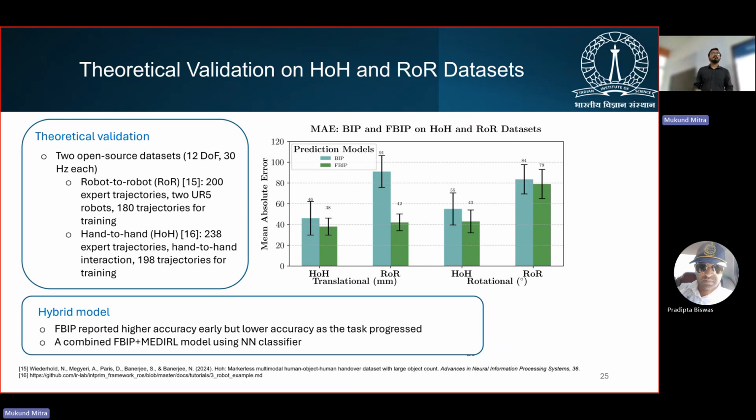So it's like that. And how are these obtained? By some IMUs of the robot? Yeah, so basically, the robot has its own SDK through which we could get the robot coordinates. For the hand, we have used multiple sensors. First, we used a simple Google MediaPipe to track the hand coordinates. Then we used an IMU sensor, basically a Vive tracker, to obtain the XYZ, roll, and pitch of the hand coordinates.